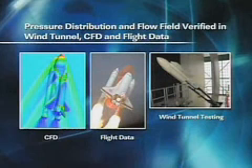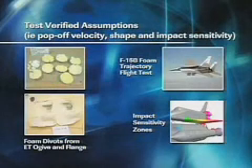So we have run that work, and we have been able to show that our computational fluid dynamics, our flight data, and our wind tunnel data all line up with each other. So we feel really good that we've got the basic underlying flow field done properly. The next chart. Then there are a lot of assumptions that go in the model, and we've done a variety of tests in order to understand that. At the Marshall Space Flight Center and at Michoud at the tank facility, they've been doing quite a number of tests, trying to understand how divots come off the tank for foam, and we've been doing equivalent tests for ice at Stennis and at Marshall Space Flight Center.